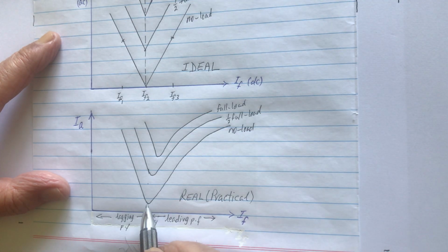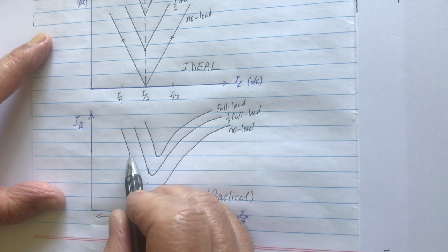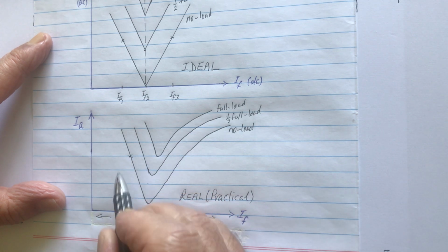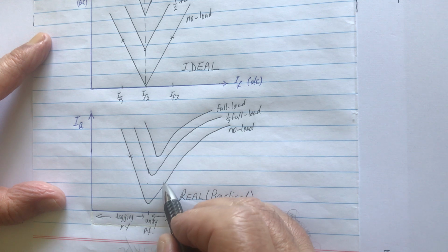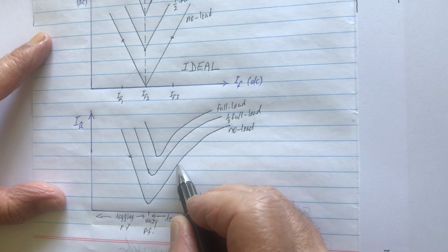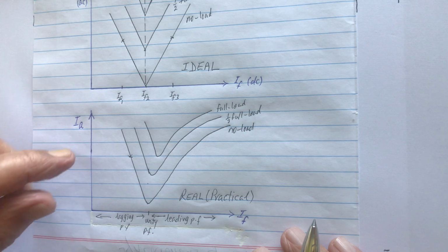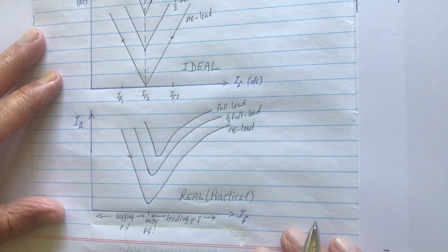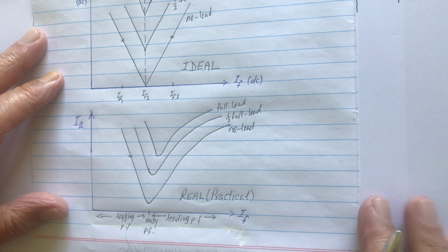So here, even at no load, at unity power factor, the current will be minimum. So if you're working at a point here, let's say, and you increase the excitation, IF, the current becomes minimum at unity power factor, and then starts increasing at a leading power factor. When you have a leading power factor in a plant, then you're going to improve the overall power factor of the plant.